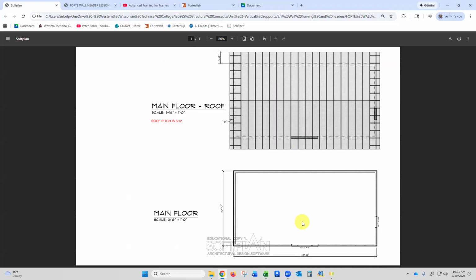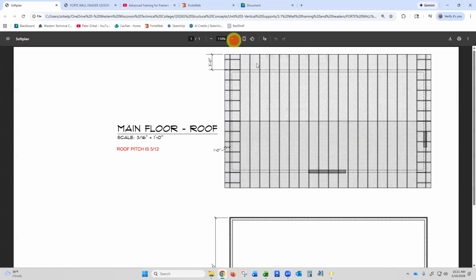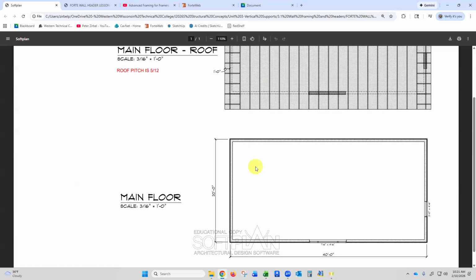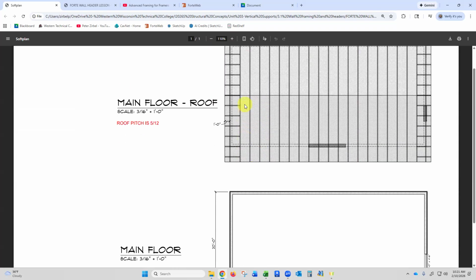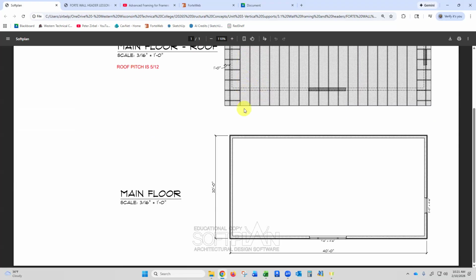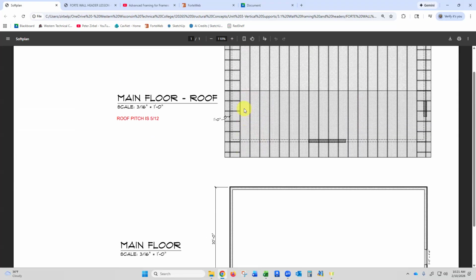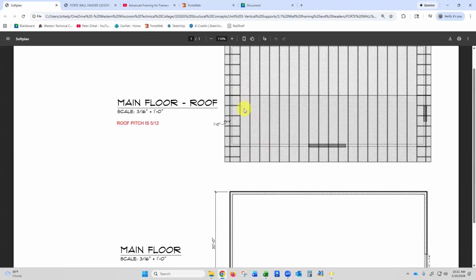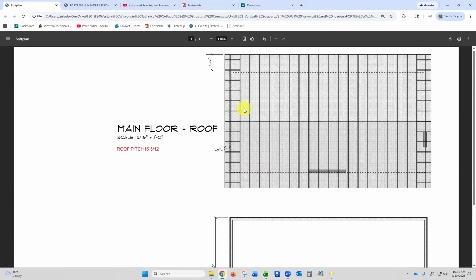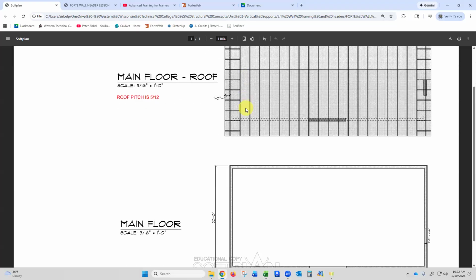Remember the last slide on my PowerPoint? Let's zoom in so you can actually see it here. That would probably help you get a good answer. It's 20 feet and a 3-foot overhang. It's going to take half of it. Okay, let's have somebody come up with a number and raise their hand. It's not 26. It's not 23. 13. Yes. How did we get 13? Half of the distance plus the overhang.